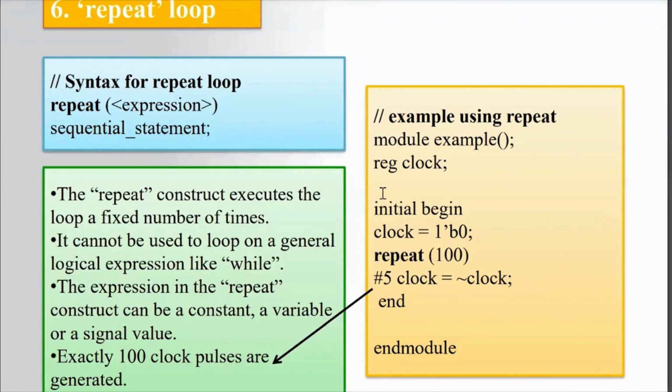Mainly we write begin end whenever we have more than one statement. Okay. No idea. We'll discuss those things today: what begin end means, what blocking and non-blocking assignments are, and the difference with fork join. Before that, we'll see how many ways we can write the clock. How can we generate the clock?